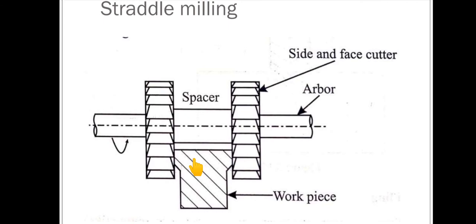But if I use two side and face cutters at a time, then in a single run, at a single cut, I can perform both side operations.